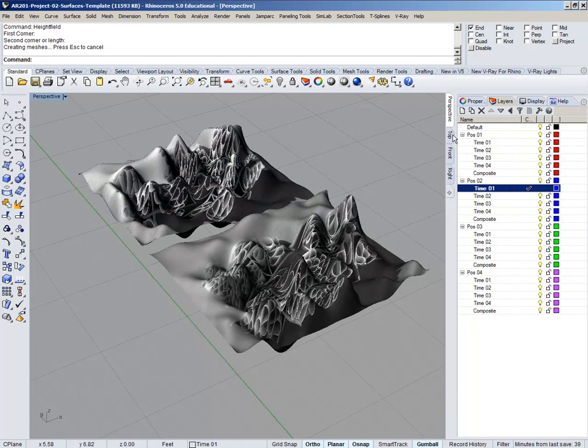But yeah, we realize that a lot of you guys might not be too comfortable with Rhino. So it's going to take a little bit of time. We're only using one command. So the important things are that you use the end snaps up here for that. If you don't see the end snaps, O snap, they're down at the bottom. They need to be activated. So you want to click it and make sure it goes dark so you can see them. And we're using the end snap and we're using the Heightfield command.